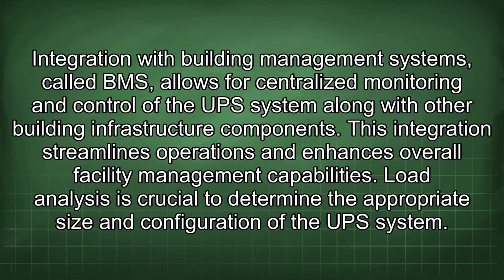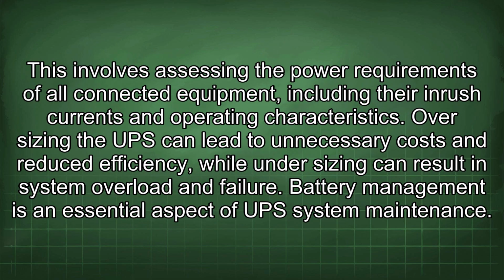Load analysis is crucial to determine the appropriate size and configuration of the UPS system. This involves assessing the power requirements of all connected equipment, including their inrush currents and operating characteristics. Oversizing the UPS can lead to unnecessary costs and reduced efficiency, while undersizing can result in system overload and failure.